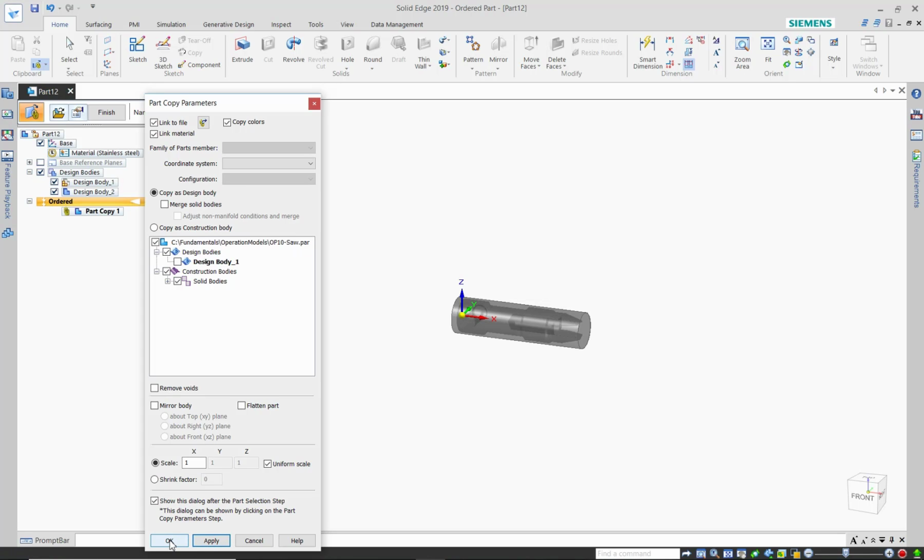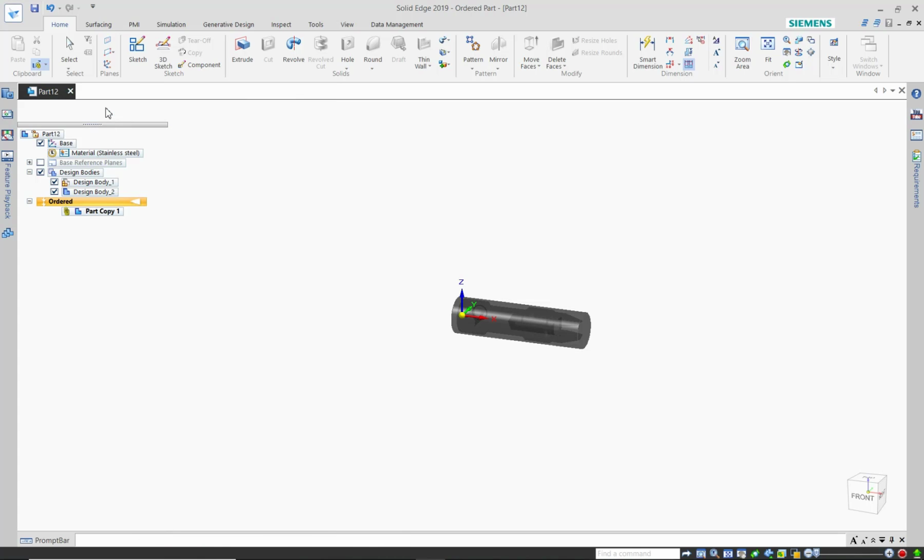We've set the material to be inherited and linked. And we renamed the bodies so we don't get confused as to which one's the finished part and which one is the workpiece. One of them needs to be activated, and if you don't know, activated in multi-body means that's going to be the recipient of cuts and protrusions and things like that. It's your target.